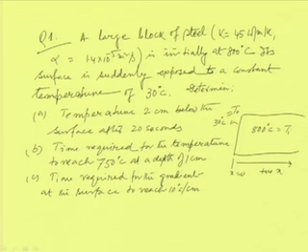So, it is a constant temperature, which is nothing but equal to T0. That is what we have been discussing in our previous case, the constant temperature condition. This body has thermal conductivity K equal to 45 watt per meter per Kelvin, and alpha is equal to 1.4 into 10 to the power minus 5 meter square per second.